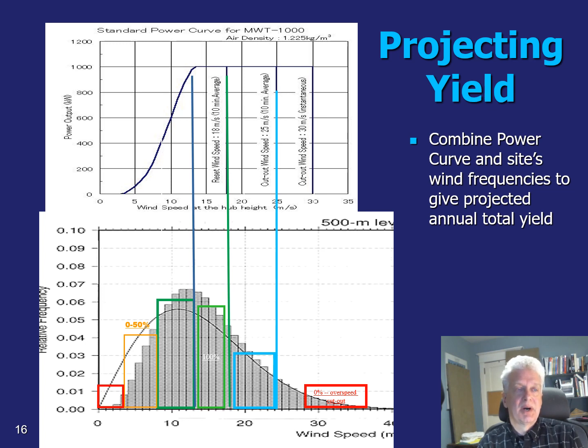In the dark green box, you're getting closer. You're in the upper half of the S curve, and there you're in the upper half of the power range that this unit can produce. Once you reach the aqua or dark blue bar, you get to the rated capacity, and somewhere just around half of the wind speeds at the site that I've taken as a sample here are in this range where you're working your way up to the rated capacity.